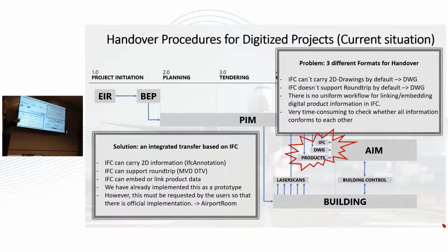The only thing we need here is this kind of substructure and elements also for equipment like doors, for example, because doors are very complex things in airports: they contain so many subcomponents you need to declare separately. You need technology like the different layers, for example, in walls, also for other components in an IFC file. Technically, it's not a huge problem, but it has to get solved, actually, so that we can do this with the standard software on the market.